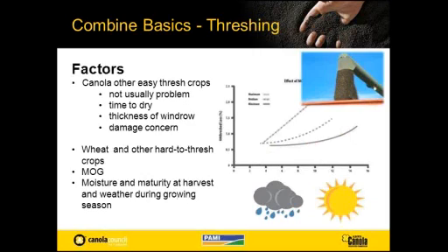Now, some of the factors, obviously, in canola, it's usually not that big a problem. A lot of threshing is done by the auger up the feeder and into the inlet, and then right in the threshing section, a lot of it is already done, and it just simply begins separation. There are times when threshing can be a problem, and this year was a good example early on where crop was cut and in 3 or 4 days it was dry. Some of those pods did stay a little tougher and didn't break apart quite as easily. Took a little more threshing action to get the seed out of them.